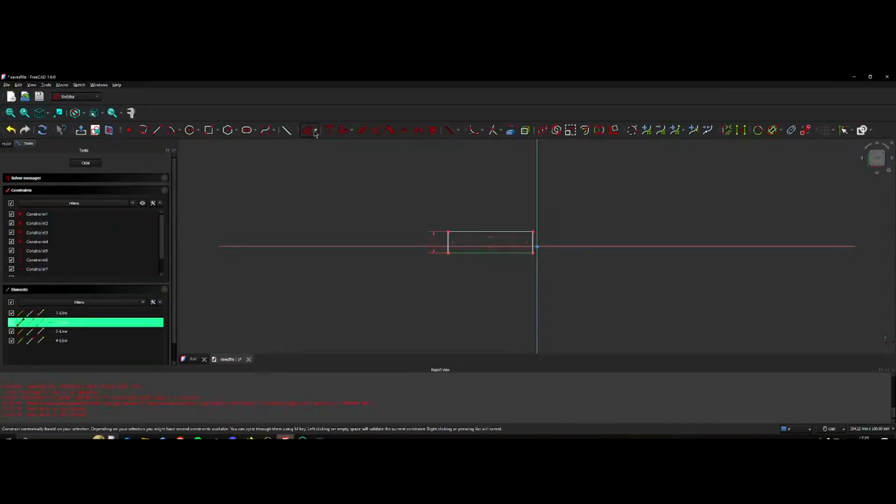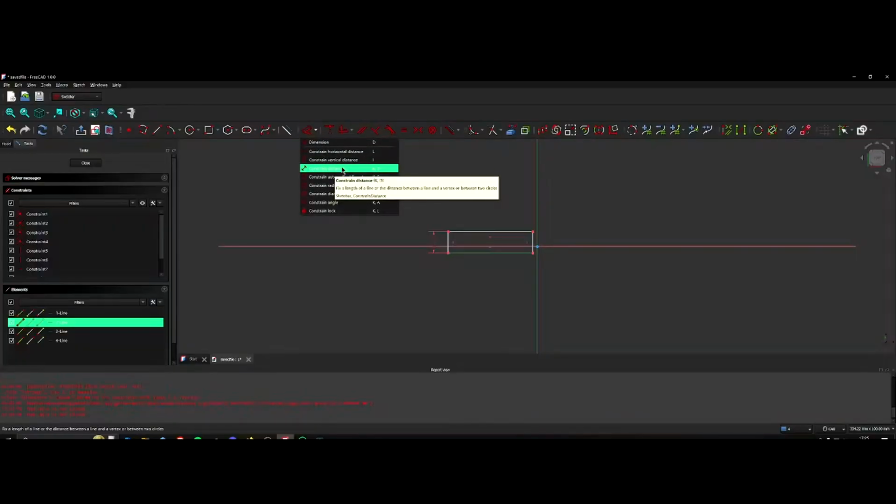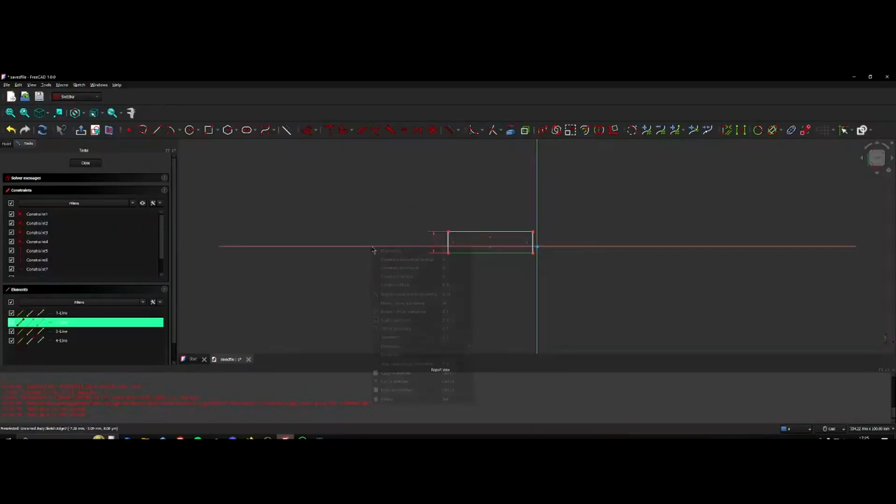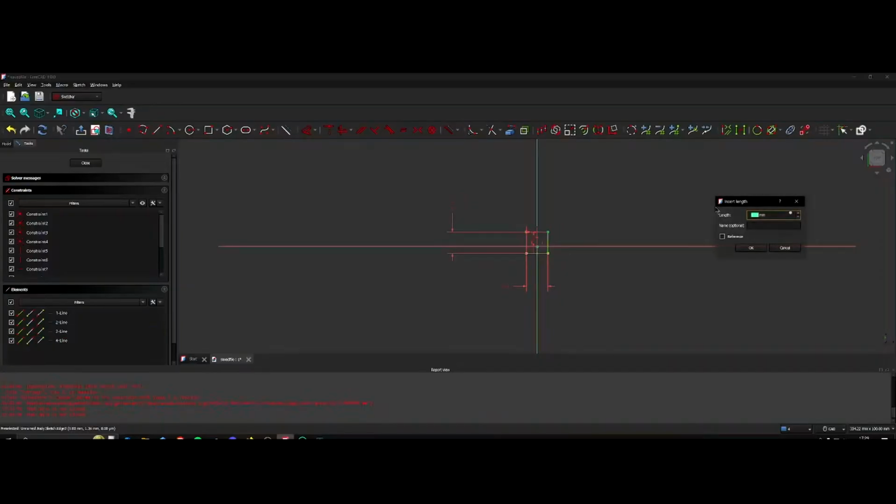Once you have defined your measurement and confirmed it by selecting OK, the shape should automatically transform according to your input measurements, and you'll get a red constraint line denoting said measurement, which you can move out of the way by clicking and dragging it. Now, what constraints also allow you to do is define a specific distance from a point in 2D space. So, if I wanted my square to be perfectly centered, for example, I would constrain the length and height, but I would also add the same constraints relative to the central point. In this case, half length and height from the center.